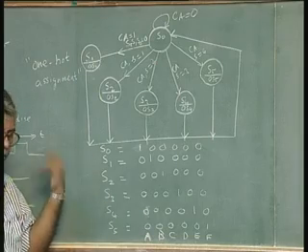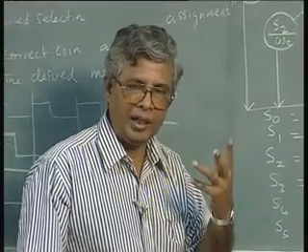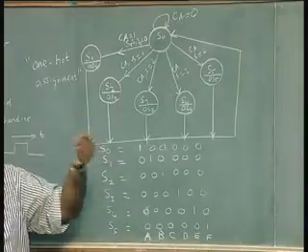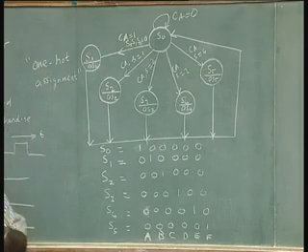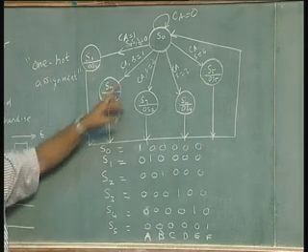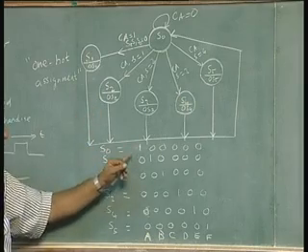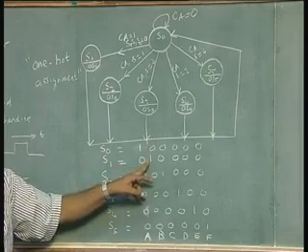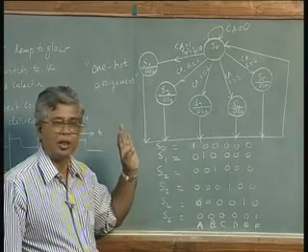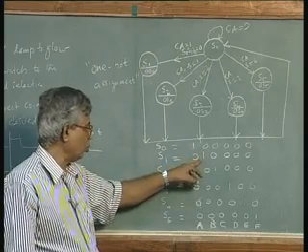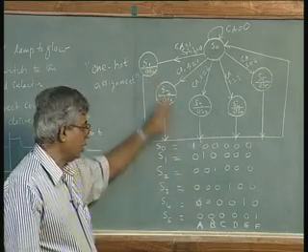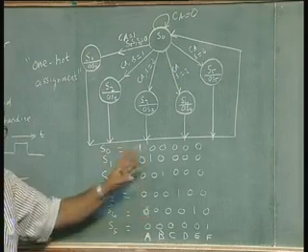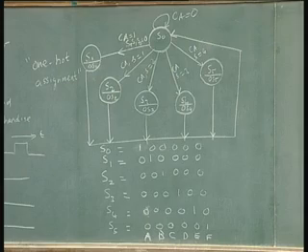And in our case, we are choosing a PAL with a large number of states, a large number of flip-flops, and since we do not have enough number of states, we are going to assign one flip-flop per state. That is the one hot assignment procedure. So, that way I am going to make the flip-flop A active for S0 state, and output of that will be the S0 output. So, whichever flip-flop is active, that can be the corresponding output also. That is the advantage. If S1 is active, that means we are in state S1, which is YS1 state. That means output of flip-flop B can be the output YS1. That is the advantage of this method.